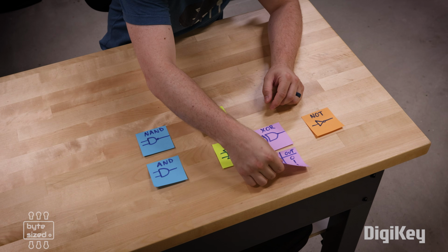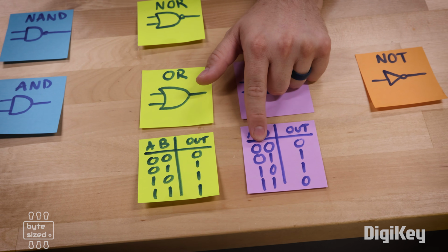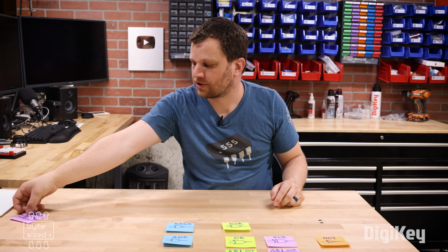Finally, I want to introduce one last logic gate. It's called an exclusive OR gate. It works very similarly to the OR gate, except that if I want the output to be 1, I need the inputs to be exclusively different from one another. When the inputs are the same, like 0, 0 or 1, 1, the output is 0. When the inputs are different, I get a 1 on the output. And of course, we can always add an inverter to the output, creating an XNOR gate.